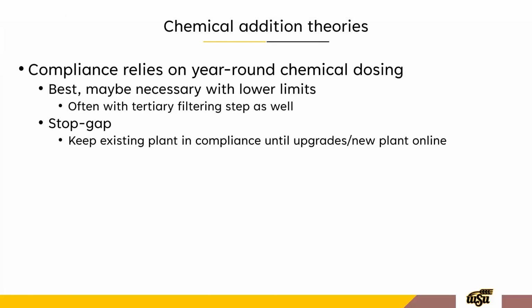If you get really, really tight phosphorus limits, maybe under 0.7, 0.8 milligrams per liter, chemical becomes almost a necessity for phosphorus compliance. But at the limits that are going to be faced by Kansas plants, at least as far as we're aware of at this point, typically biological phosphorus removal is within the realm of usable solutions.